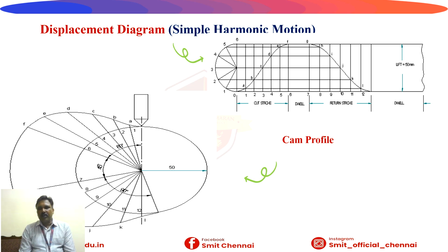Then with the help of the compass, we have to take all the distances from the displacement diagram only. That's why I already told, without the displacement diagram, it's very difficult to draw the cam profile. Using the compass, you have to take the distance. For example, on the left hand side of the outstroke, you have to take 1 to A. We take it in the compass, keep it at the center point 1 in the cam profile and mark the intersection. Then followed by 2 to B, 3 to C, 4 to D, 5 to E, 6 to F.